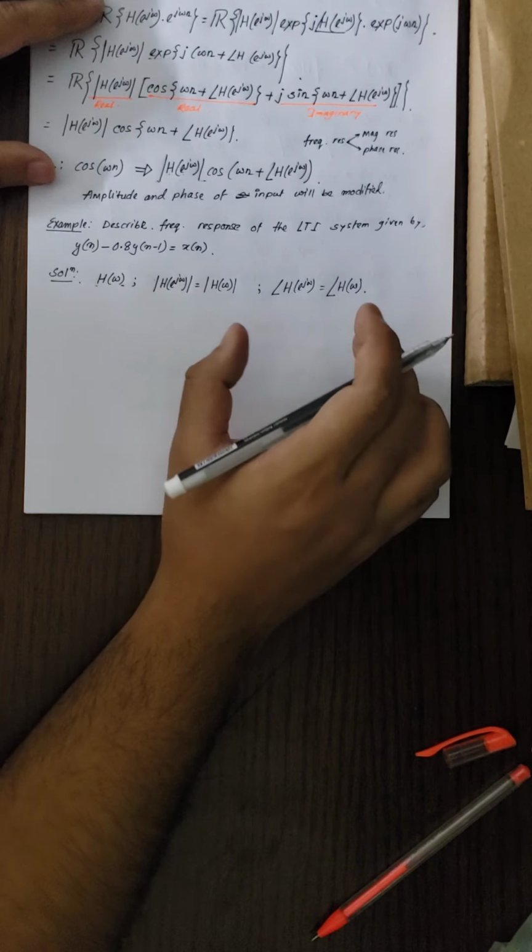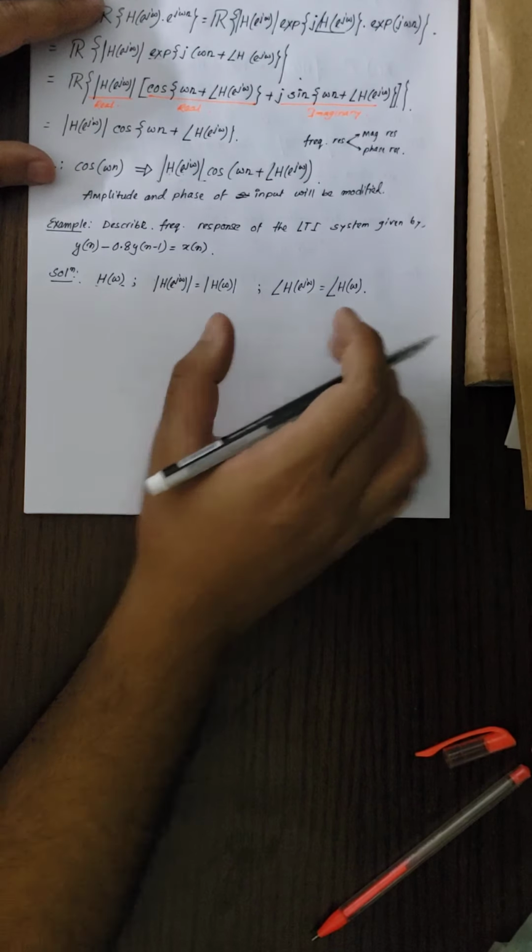In order to get to these values, first we need to apply the direct Z transform to this expression. So y of n Z transformed will become Y of z, minus 0.8 times z inverse times Y of z, since it is delayed in the time domain by one sample. So in the z domain, the term z inverse is multiplied times Y of z, and x of n will have a z transform of X of z. So now we can write Y of z, taking it as the common factor, times (1 minus 0.8 z inverse), is equal to X of z.